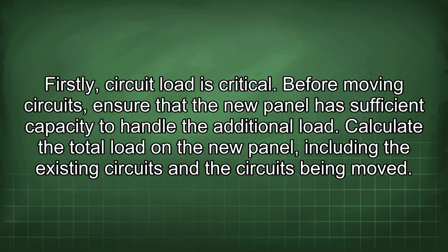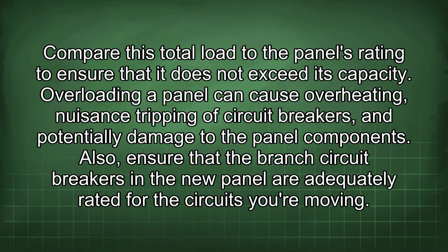Calculate the total load in the new panel, including the existing circuits and the circuits being moved. Compare this total load to the panel's rating to ensure that it does not exceed its capacity. Overloading a panel can cause overheating, nuisance tripping of circuit breakers, and potentially damage to the panel components. Also, ensure that the branch circuit breakers in the new panel are adequately rated for the circuits you're moving.